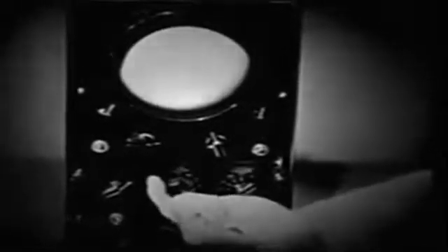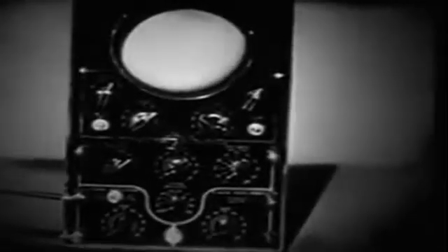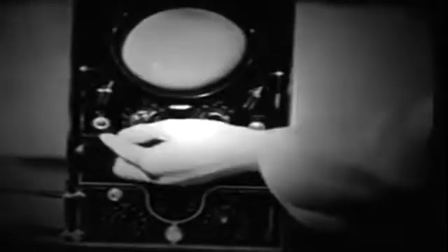The exact frequency desired can be obtained by using the fine frequency control. To study its characteristic patterns, a 400 cycle source is connected to the vertical amplifier. We turn on the beam, adjust intensity and focus to get a sharp spot. Not too bright. Then, properly center the spot.